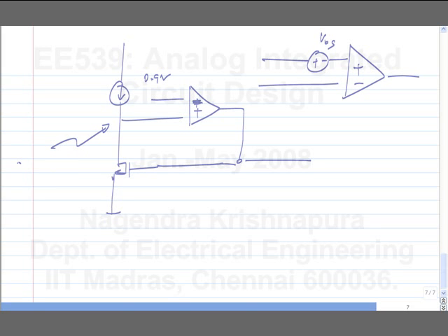So you can't do much to the random offset. Now if the random offset is very high, then you will have to design this particular auxiliary op-amp for a smaller random offset. This is not likely to be an issue for biasing. If you are using this circuit only for biasing an op-amp, or another simple low precision circuit, it's not an issue.